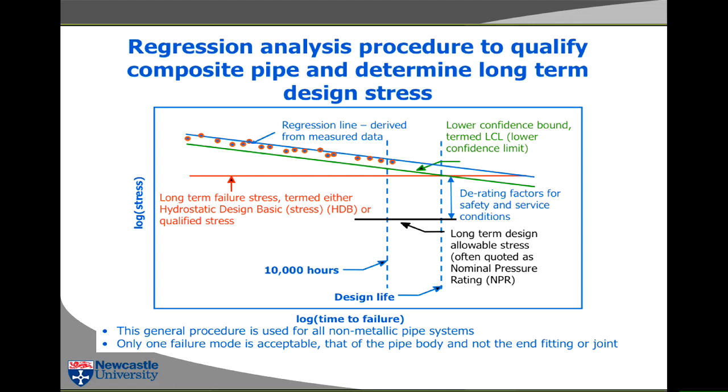So you understand this idea of the best fit straight line, and I often ask this question in exams. However, the best fit straight line isn't a basis for design, is it? Because you can see that not all of the points lie on it. You wouldn't expect them to, because the product can be variable. In fact, the product variability is one of its properties.